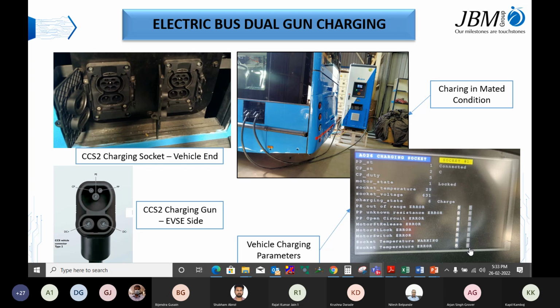इस कंडीशन में आपकी एचवी ऑन है, सब कुछ ऑन है? क्योंकि जब व्हीकल चार्ज स्टेट में जाती है तो जो करंट और वोल्टेज डिमांड है वो पहले ही बस चार्जर को सप्लाई कर देती है। But इस केस में बस की साइड से वोल्टेज की डिमांड तो आ गई but करंट की डिमांड नहीं आ रही है। ऐसे केस बहुत कम हैं, but कंडीशन ये हो सकती है कि बीएमएस ने करंट डिमांड मांगा ही नहीं है, या कुछ एरर हो सकता है जिसको डायग्नोज करने की नीड होती है। जैसे 30-40% भी एसओसी है, उस केस में वोल्टेज डिमांड तो 100% आ रही है but करंट डिमांड नहीं आ रही है। ये sort of इंटरलॉक है, जब तक वोल्टेज प्लस करंट की डिमांड नहीं आती, तब तक चार्जर की साइड से आउटपुट नहीं है।